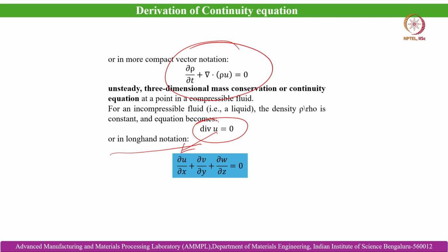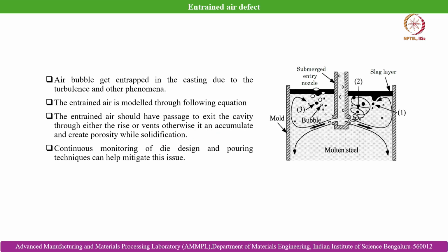This is of very much importance in die filling analysis when we are talking about the flow of incompressible fluid, when density is not changing with space and time, and because we are also talking about steady incompressible fluid. That time this continuity equation comes into play. However, when solidification is involved, that means mass transfer is happening, then we have to use the conservation of mass in that case. We will come to that. We will also discuss the corresponding case studies.